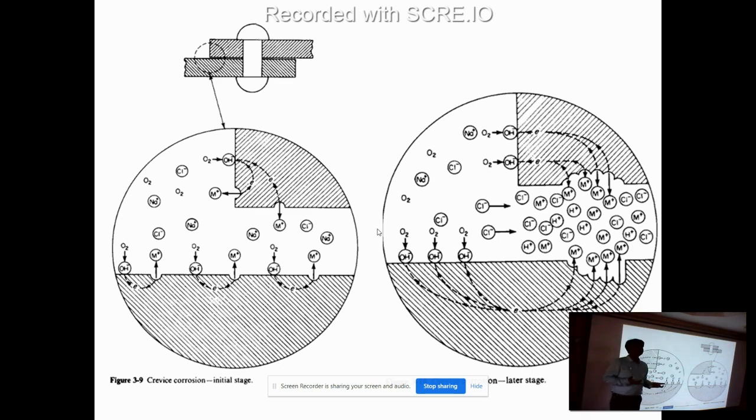More corrosion again. So if you look at the place, I just took this part and showed you. See, unknowingly, this entire portion of the top metal will be lost. Now, can you identify if something is loosened here? Because that is happening inside the two metals. Slowly it is corroding. So ultimately, this entire mass is removed until it becomes loosened. And if it is getting loosened, this contact will be slowly broken. Derailing.